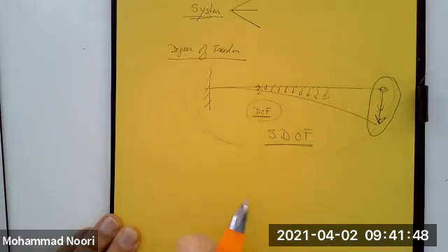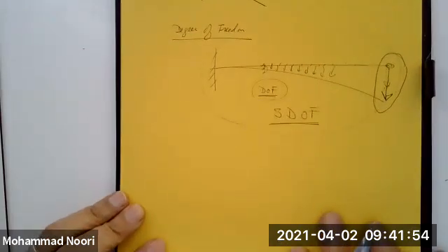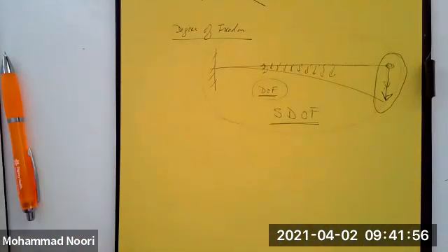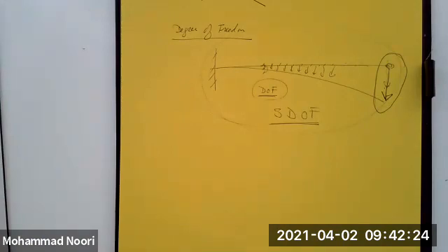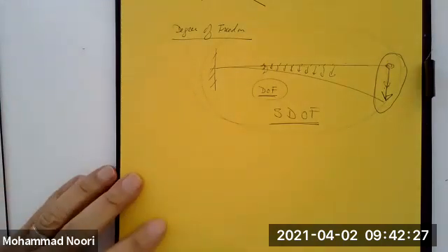And in fact, the first thing we do in studying mechanical vibration is figure out how in the world I can identify, in any system, a single point, a single degree of freedom, whose motion can be related to the other members, the other degrees of freedom. In other words, other degrees of freedom will be dependent on this degree of freedom. So the structure can be represented by only one degree of freedom, or a single degree of freedom. This is a terminology that we'll get to.